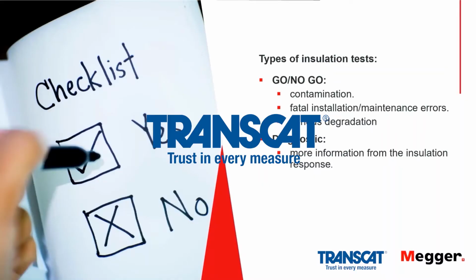Okay, types of tests. Before we go into the instrumentation and the testing, it's always important at the beginning of a job to just take a couple of moments to think about the goals of your testing and to plan a little bit. And there are two major testing goals where insulation testing is concerned: the go, no go, or pass fail type of test, and the diagnostic type of test. So it's helpful to just think, which are you going to do?